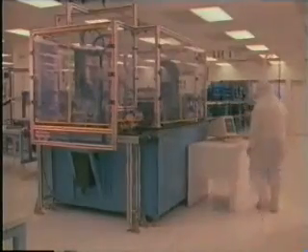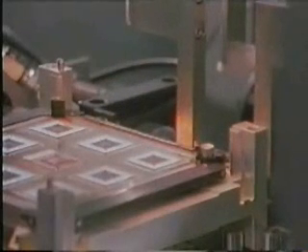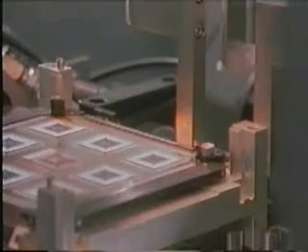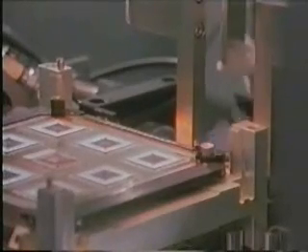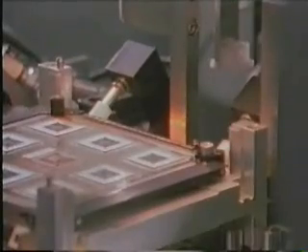In a robot work cell, flux is dispensed on the 2 PowerFlex bonding pads. The power consumed by the multi-chip unit is brought in through a power connector. The PowerFlex circuit, containing 4 copper conductive planes, is aligned with the large PowerFlex pads on the multi-chip unit.